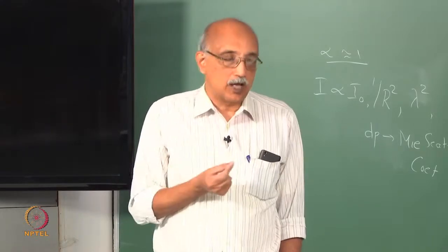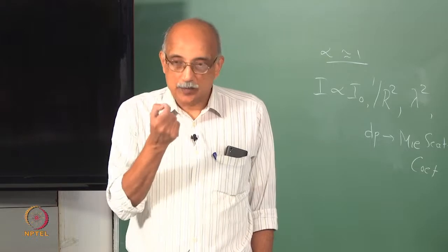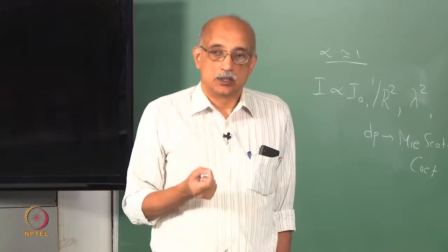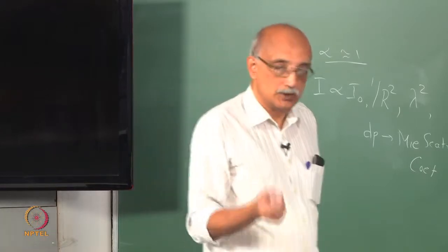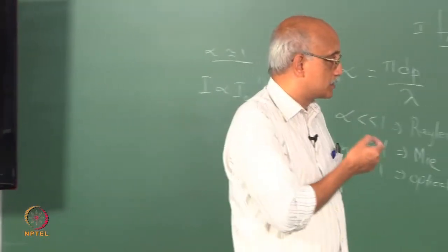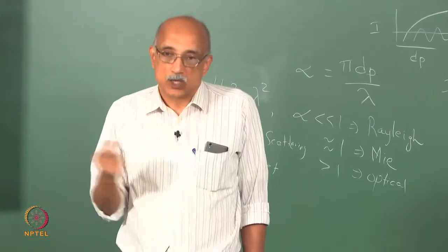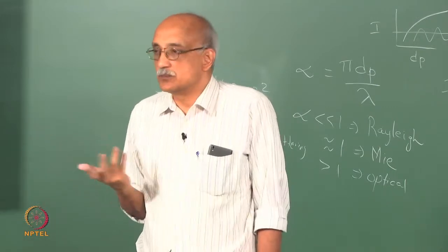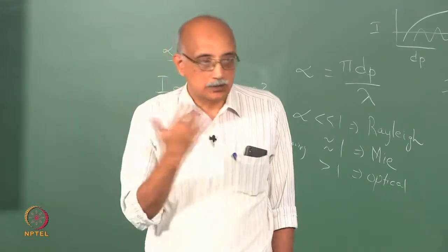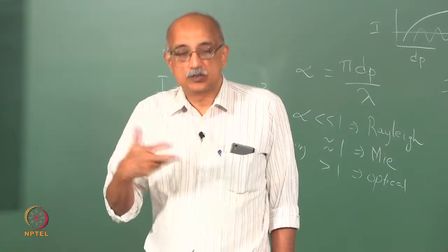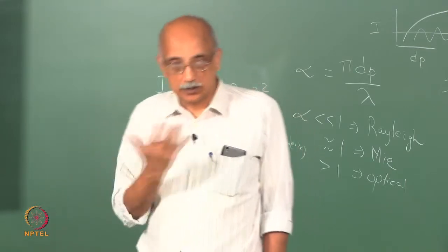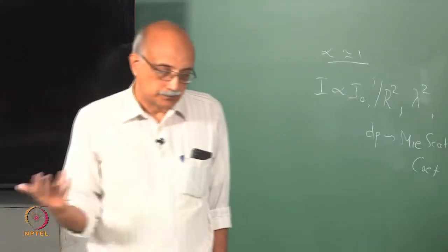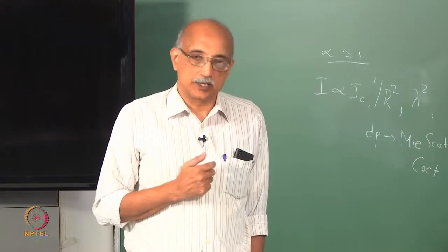So a critical requirement is that the small sample that you take must be a fairly good representation of the whole, and the only way you can assure that is by making certain that the sample is uniform. How do you do that? Well, for example, with liquids, use stirring. It is a simple way to make particle distribution uniform, or you can use more sophisticated techniques involving high frequency vibrations and so on. In terms of an air sample, we kind of talked about this a little bit yesterday.